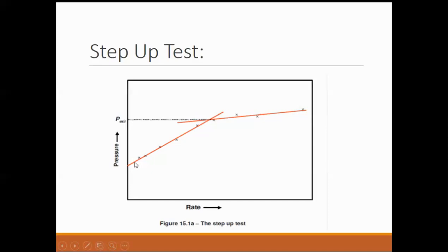Even if it is a massive fracturing campaign, there is no subsidence being caused, because the volume that you create in a particular formation with the fracture is quite insignificant compared to the volume of rocks overlying it, right? So even if you create a small volume, because of the overburden stress, the overlying rocks or the bottom rocks expand and put pressure on the closed fracture. That expansion is very negligible because the volume of the overlying rocks is so large and your fracture volume is quite less.